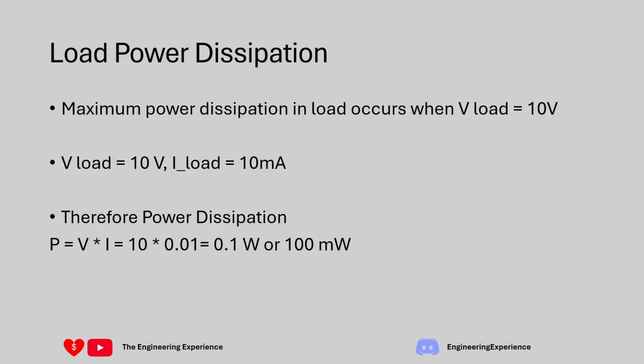So what this question is telling us is that for a 10 milliamp current source, the series resistor, which is not our load, is going to get 10 watts of power. But the actual thing that we care about, which is the load, is only going to get 100 milliwatts of power. Now, if you do the maths, you can calculate the efficiency of this circuit is roughly 0.1%, which is very, very low. So you wouldn't want to use this circuit in any real application unless the current you're trying to produce is very, very low. Otherwise, it would not be worth it.